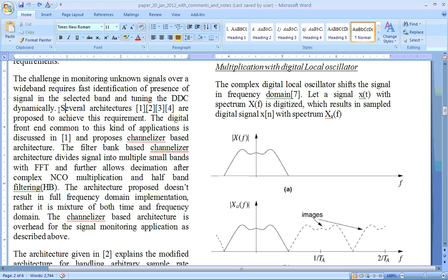Take a 64-point FFT core. The 64 FFT outputs come out as X of 0, X of 1, and so on, all the bin outputs, and there is a time domain variation of those frequency outputs. FFT as such converts time domain to frequency domain. In one snapshot you get the values X of 0 to X of 63. But as you keep doing the FFT, on X of 0 itself you keep getting multiple values. You treat that as a time domain signal, and that becomes one filter output. Like that you have 64 filter outputs.